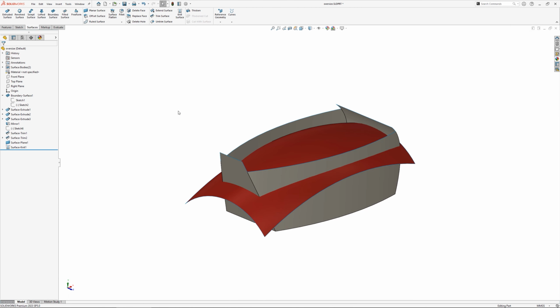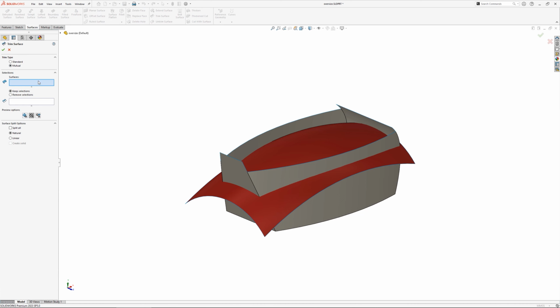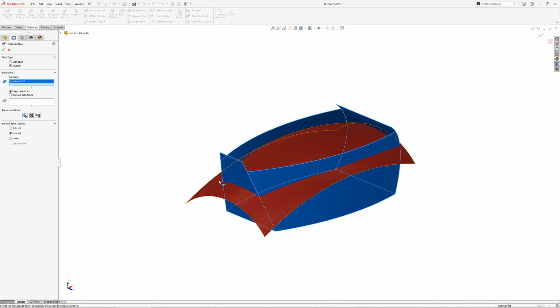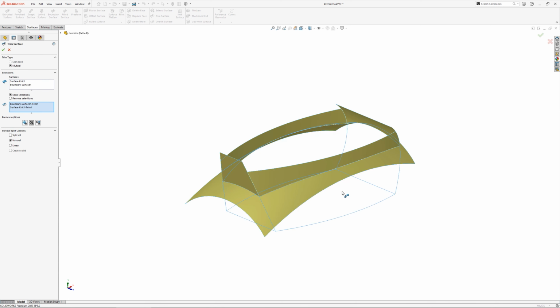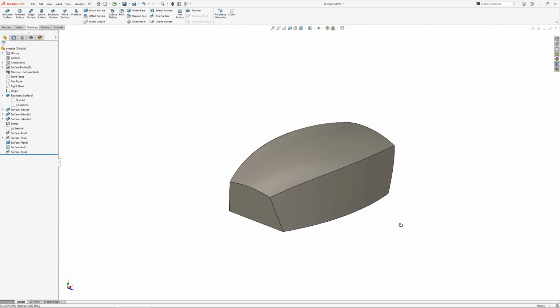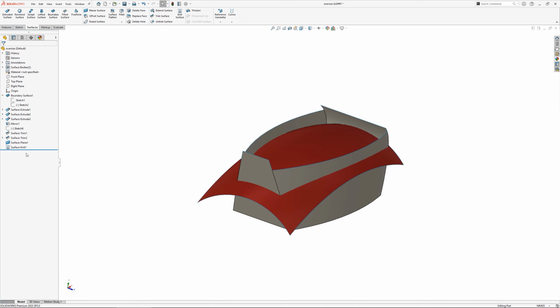A great tip when surfacing is to make surfaces that are to be trimmed or that are being used to cut away from a solid larger than they need to be. Errors can easily occur in surfacing when there is a slight deviation in edge position between two adjacent faces, and this deviation results in faces being unable to be knitted or a cut failing. Making a surface larger than it needs to be ensures that there is sufficient overlap between faces at an edge and therefore reduces the chance of a failed trim, cut or knit feature.